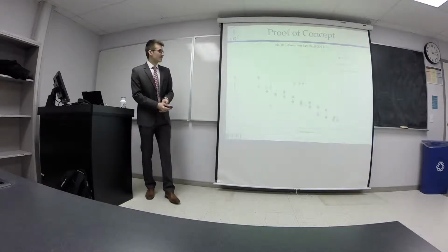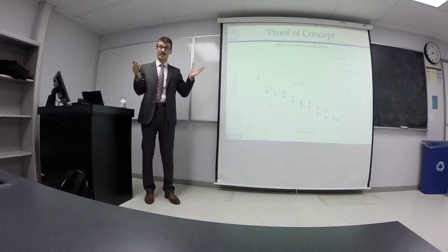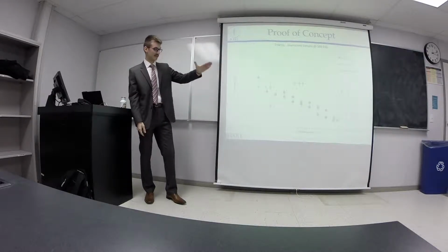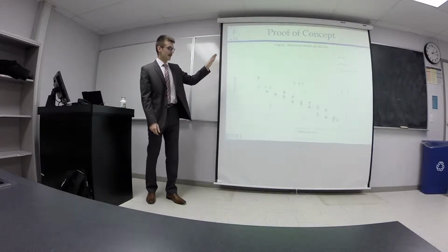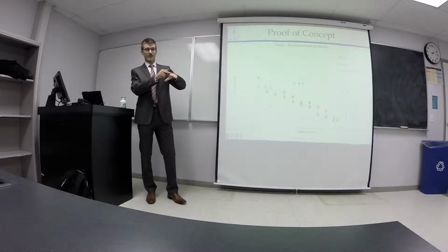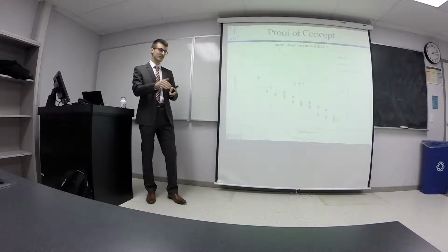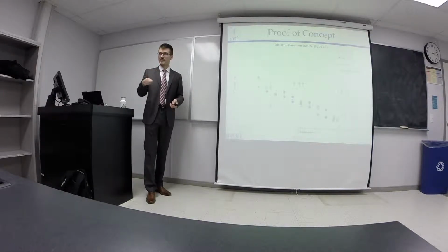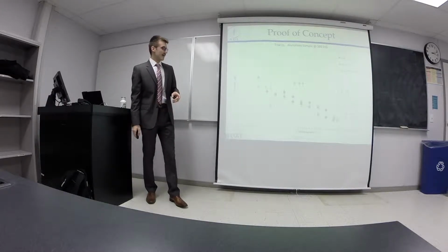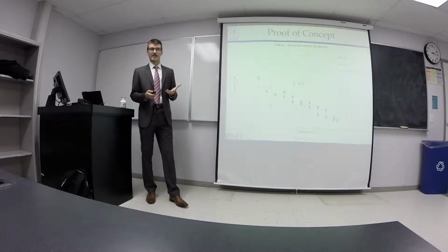So moving forward, this is what I got. The actual graph is an actual representation of the size of the sample that was detected. So the X is how long it is, and the Y is how wide it is in centimeters. The blue represents the locations of the actual crack, so this is the actual flaw that penetrated the material through, and the orange is a scratch. So it's kind of like a dent or a defect. And the green are detection signals that were generated by the eddy current probe.